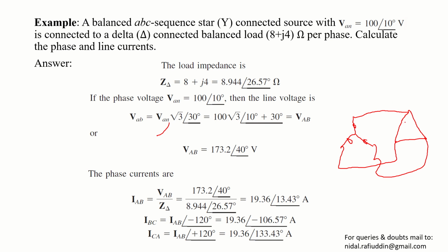So the phase current is this one. Let's say this is IP, so we can write this as IAB between terminals A and B, and this is IL. In fact, if you evaluate any one of IP or IL, the other can simply be found by multiplying or dividing by √3. So first of all, what voltage exists between, let's say this is terminal A dash and this is terminal B dash? What is the voltage that exists between terminal A dash and B dash?